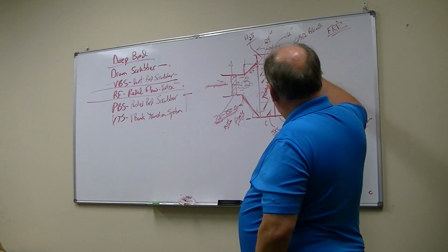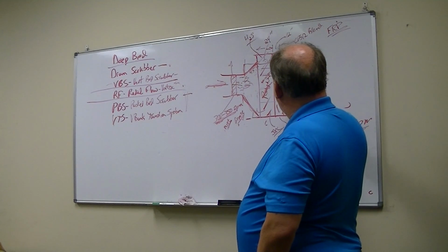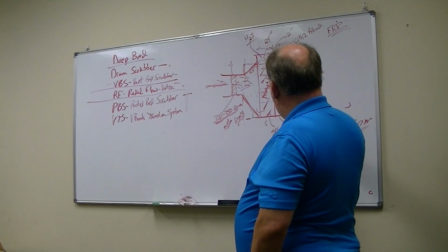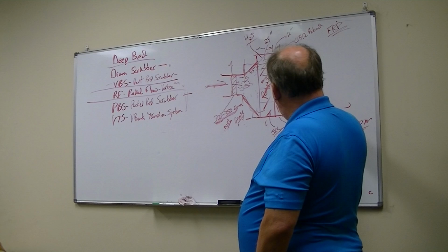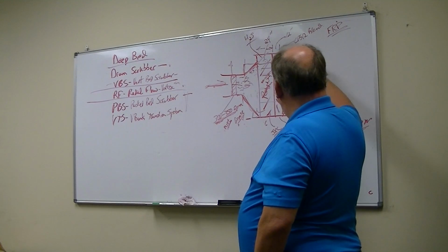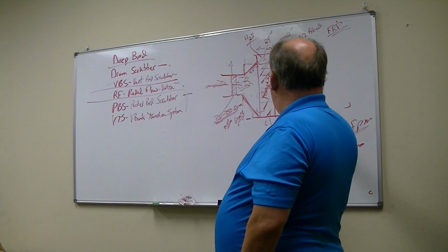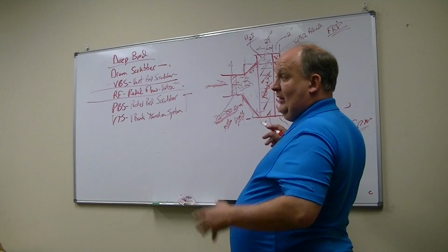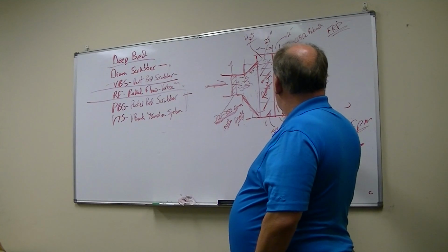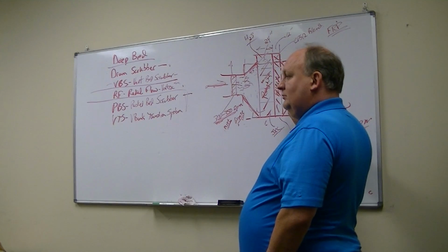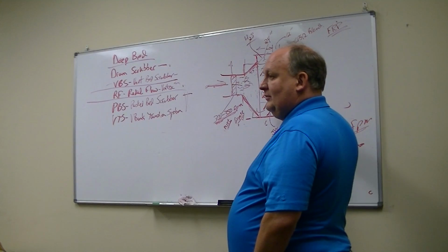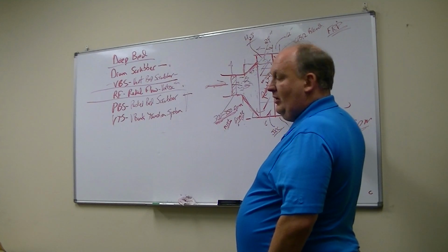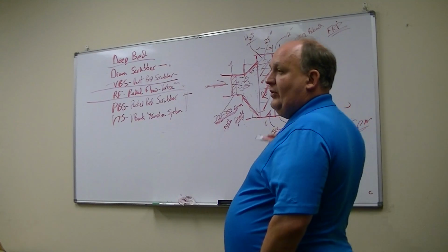Anyway, so we have to have a plenum space here for the air to go through. Again, this is going to be from the bottom to the opening of the hole in the wall, like this. This is a lot harder to maintain the 45-degree angle here because it depends on the system: the bigger the system, the more room you get. So usually this is more like 30 degrees or something like that. You just can't have this fan right up against the screen. You've got to be able to get some air to flow down like that.